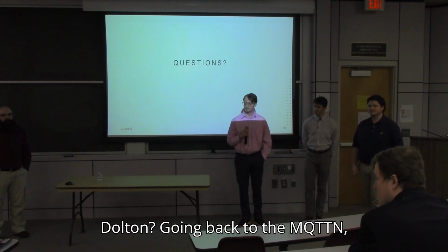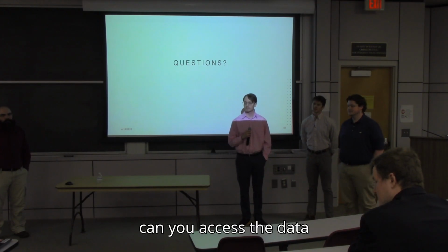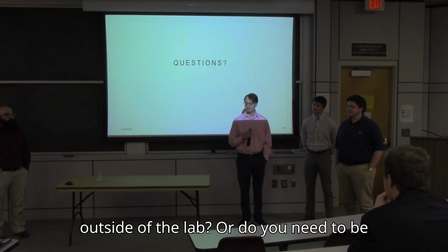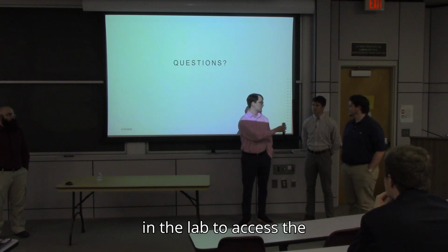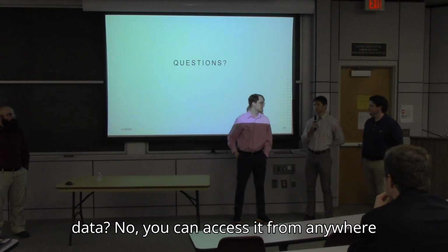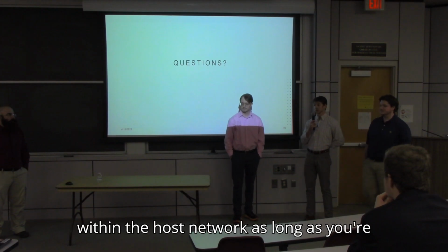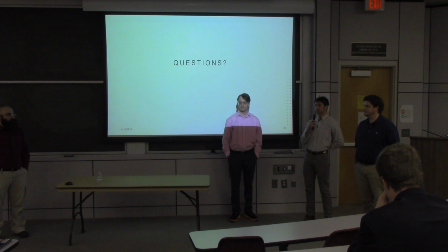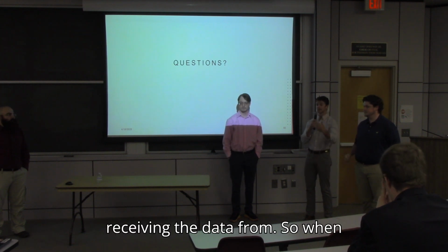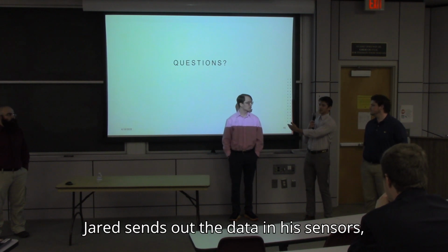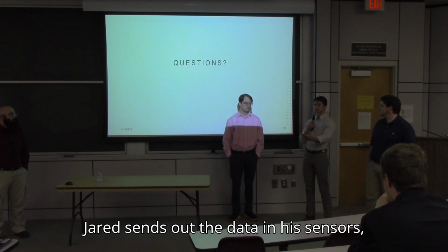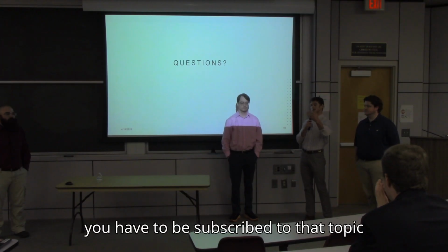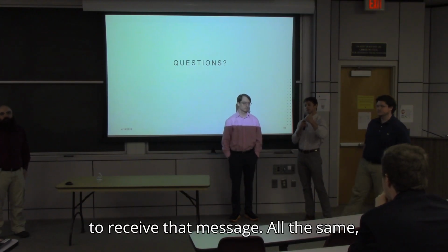Dr. Dalton, going back to the MQTT, can you access the data from outside of the lab, or do you need to be in the lab to access the data? No, you can access it from anywhere within the host network as long as you're subscribed to the same topic that you're receiving the data from. So when Jared sends out the data in his sensors, he sends it out via a payload, and you have to be subscribed to that topic to receive that message all the same.